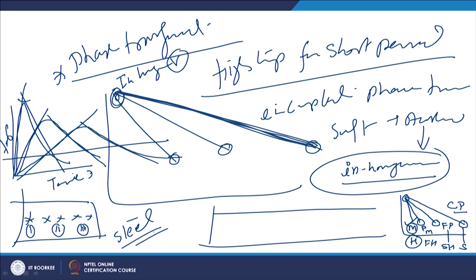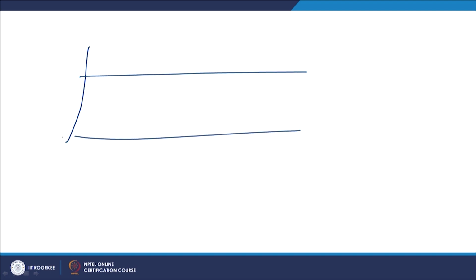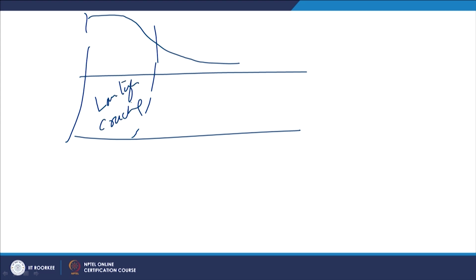So the different zones of the same steel will be experiencing different kinds of phase transformation and accordingly different properties. If we try to notice the variation in hardness in such cases, the zone next to the fusion boundary will be the hardest, and then hardness will keep on decreasing. The zone where hardness is very high will experience loss of toughness, and will show the tendency for cracking and embrittlement.